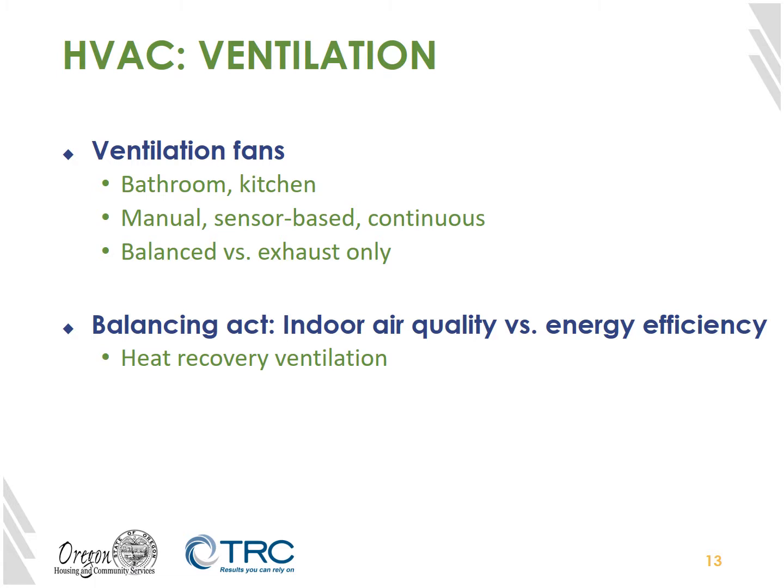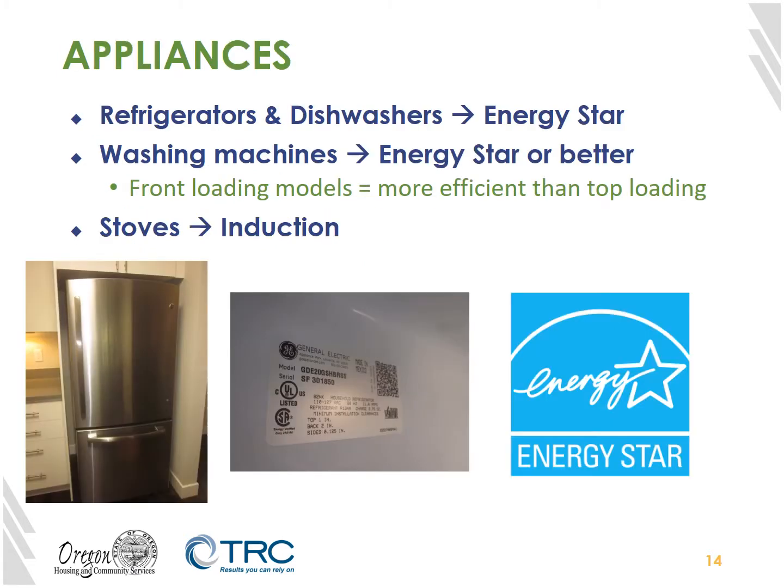Ventilation is something of a balancing act, however, between energy efficiency and health. To maximize efficiency, we want minimal unconditioned air entering the building and minimal fan use. However, to maximize health, we want to move air through the building and control and filter the source of incoming air. Heat recovery ventilation units help minimize this problem by running the incoming and outgoing air streams past one another and transferring heat between them, so that incoming air is partially conditioned already.